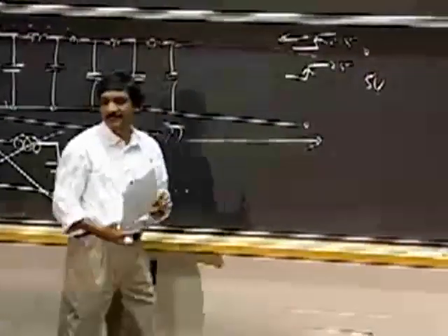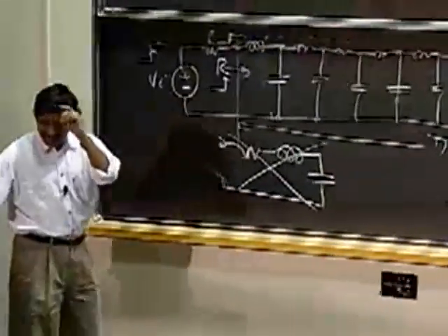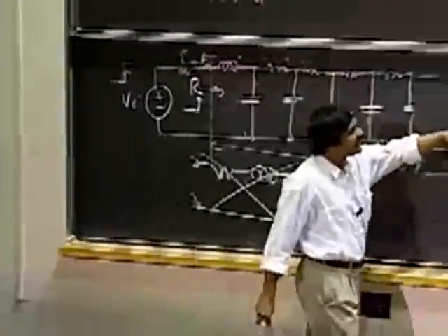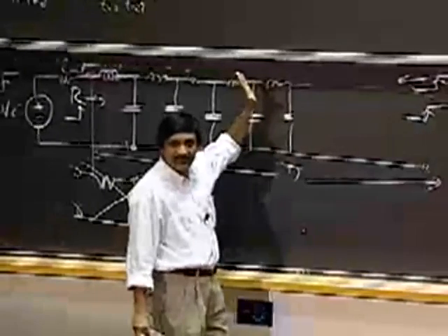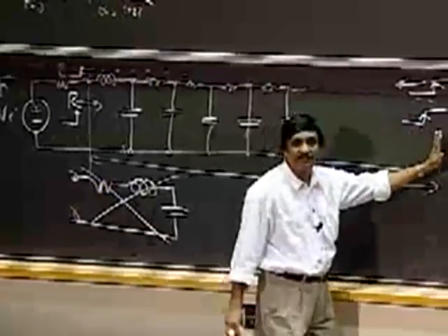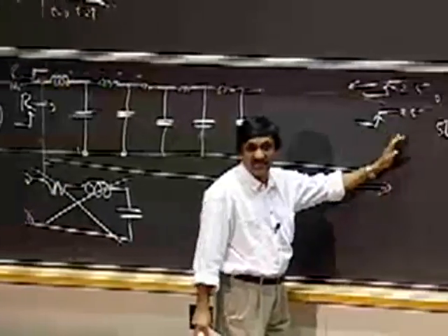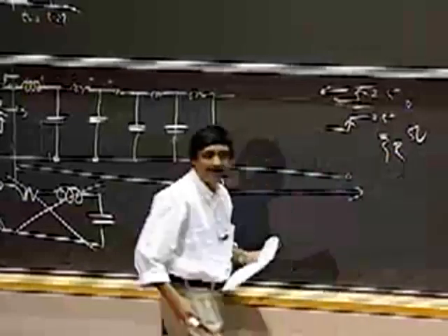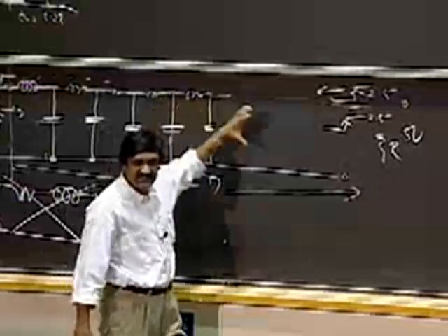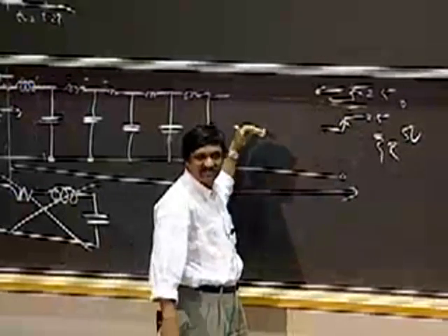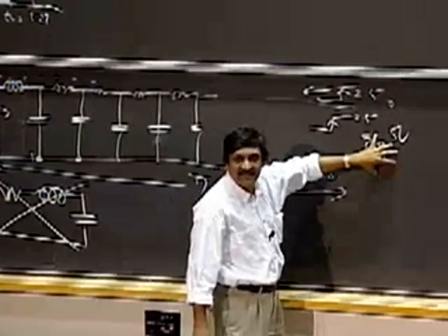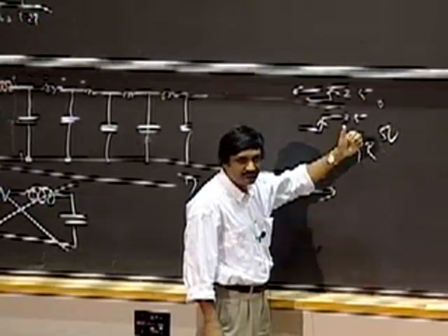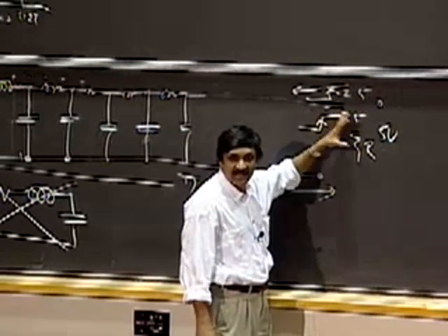Okay? Trick the circuit. So what you can do, and we'll show you a little demo here, is the reason I got this wave propagating back was that there was nothing to absorb the energy. So instead, what if I put another resistor here, R? As far as the burst of energy is concerned, it just looks the same, it's R, and goes in and dissipates in this resistor R, and guess what? I don't have any wave going back, and I'm done.